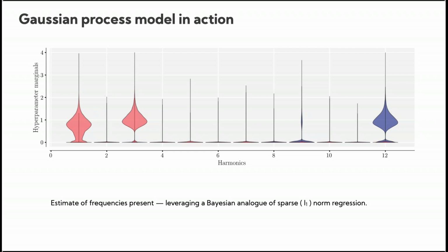And there's also the uncertainty in the calibration, right? Because this is effectively just measuring a delta, a change in millivolts. In order to convert it from millivolts to Kelvin, you need a cold junction temperature value, which also has some uncertainties.